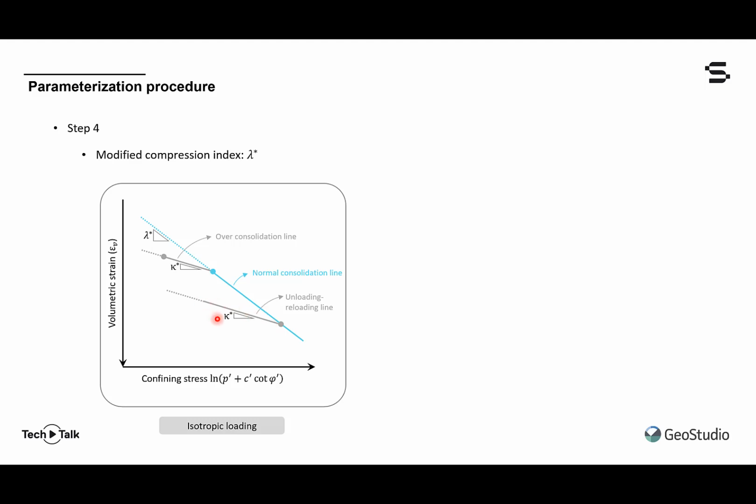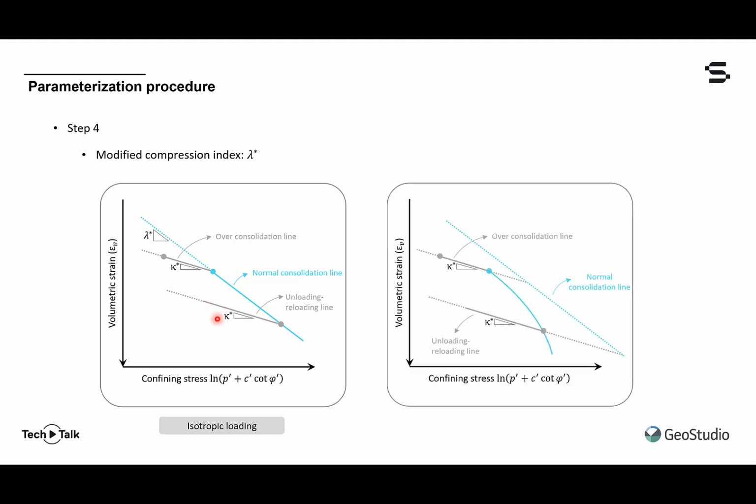However, as I just illustrated on the previous slide, it's often the case where a specimen is isotropically compressed to some point prior to yielding in isotropic compression, at which point we track along here in the volume plane. And so this blue line comprises both plastic strains and elastic strains. The elastic strains are revealed by an unloading loop.